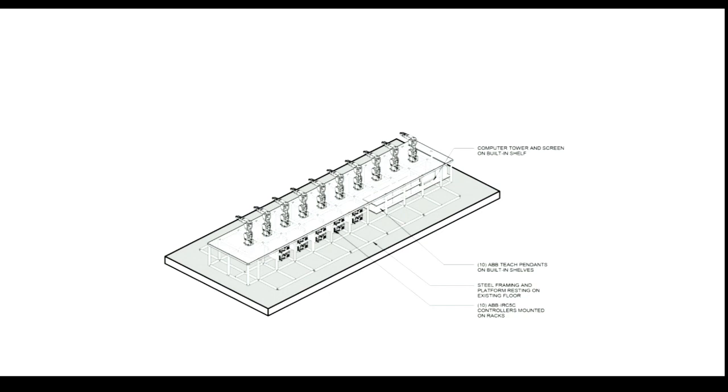This is a little bit about how the system works. So this is 10 ABB IRB 1200 robots. They each have a control box that sits over here. We had to add last-minute vents because it overheated in this enclosure. And then there's one central PC that is the mastermind, connecting all of these robots together and driving the kinematics and motion generation for it.